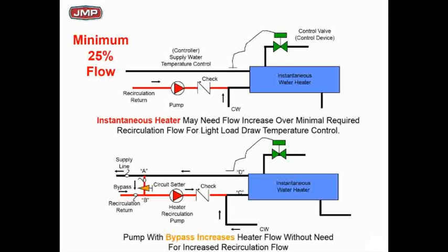The main thing you need to understand, top picture, that little green valve is a big old steam control valve. It's sized for 100 GPM, 40 to 140 through that water heater. And it's sensing temperature, supply temperature to the building. It's not sensing GPM. It's not sensing load. It's only sensing temperature.